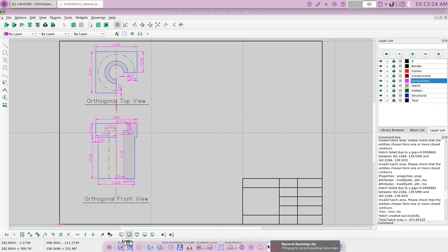Okay, to start our isometric view, we're going to be using polar coordinates. Now, these coordinates we used over here were called Cartesian coordinates, and that's quite standard for standard CAD drawing. But we're going to be using, for our isometric view, polar coordinates, that are coordinates that would be on an angle.